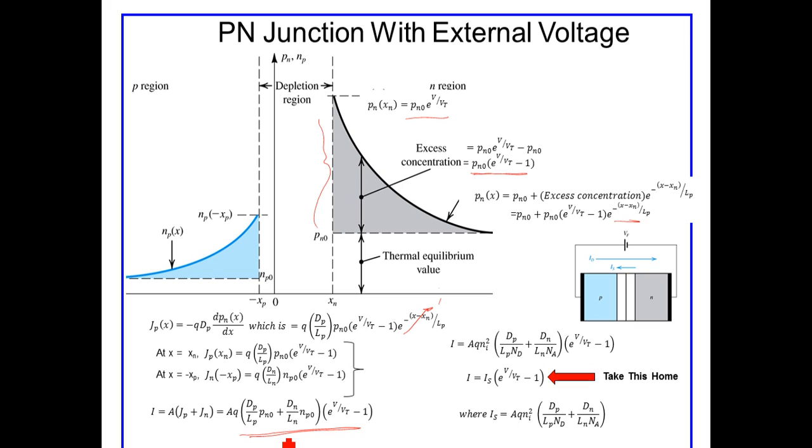Now, if you think about it, the current flowing through the depletion region has got to be the current that's flowing through the entire device. An endless supply of holes and electrons supplied by the external source continues to supply the electrons as they recombine with holes diffusing across here. As these holes are recombining with the electrons, those free electrons are being bound up.